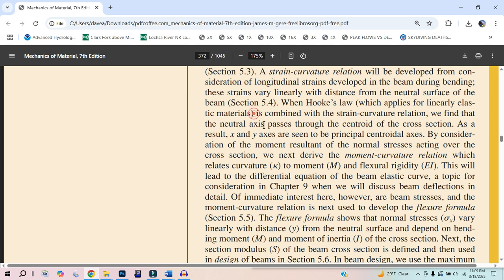And you can just apply the spring equation. Like we said, things have plenty of strength up until they no longer obey this linear relationship, where you put in the same amount of force, but then it starts to stretch out like taffy. And then maybe it gets much stronger, and then breaks. Cool, let's keep reading. So this is combined with a stress-strain curve relation.